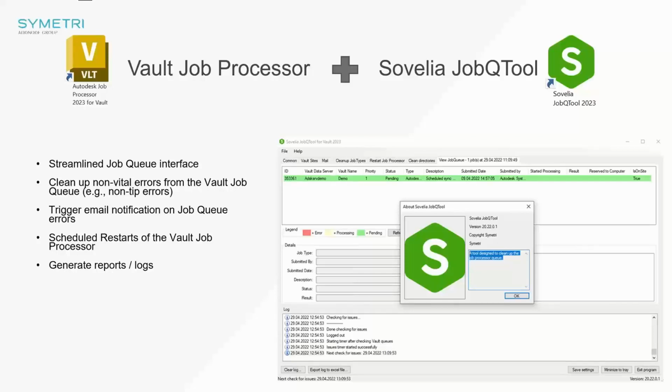A non-tip error is where a file goes from work in progress to review and a job is created to update the properties on that file, and then that file immediately goes from review to released, and an identical job is created to update the properties on that file again, in which case you get a non-tip error, which leaves an error line in your job queue. With Sovelia, we can actually just have it remove those particular jobs, because they're not jobs that require someone to go in and interrogate, we'll say.